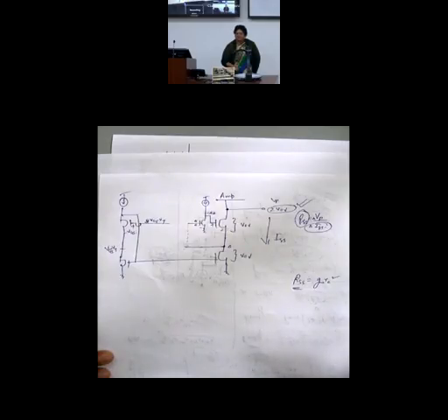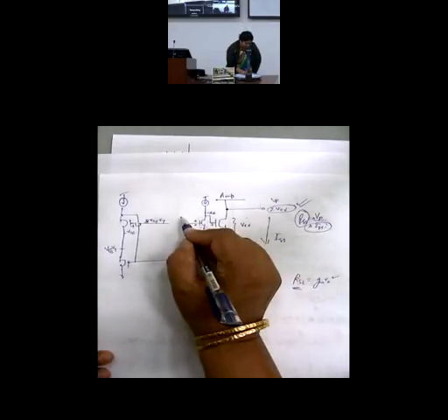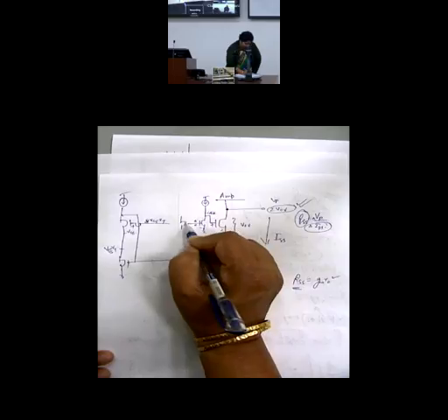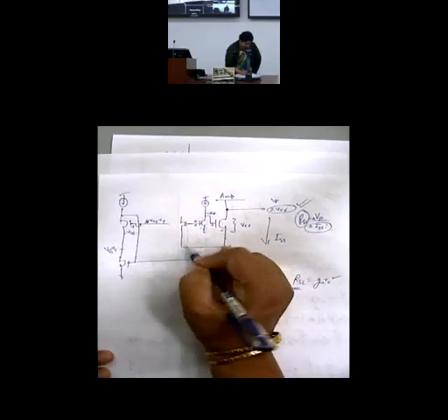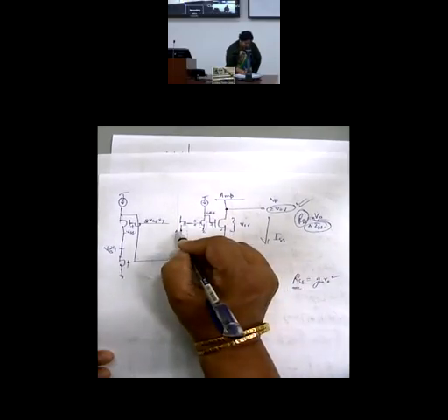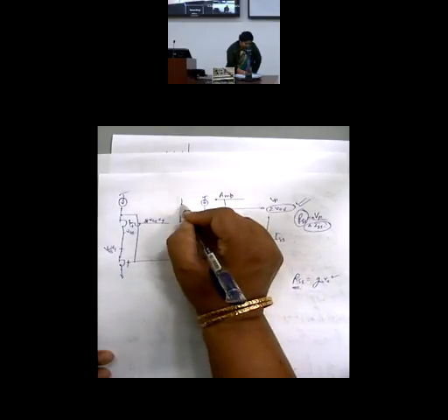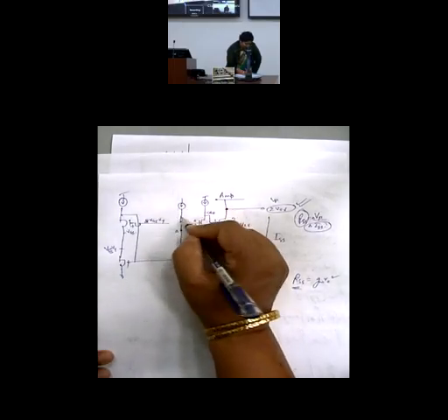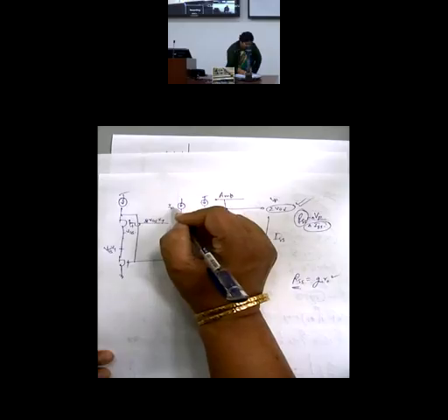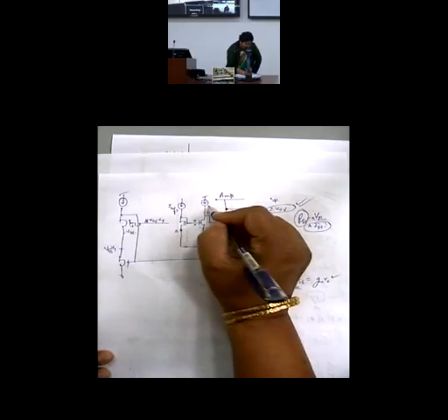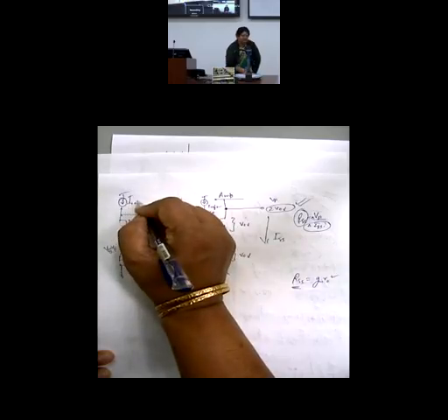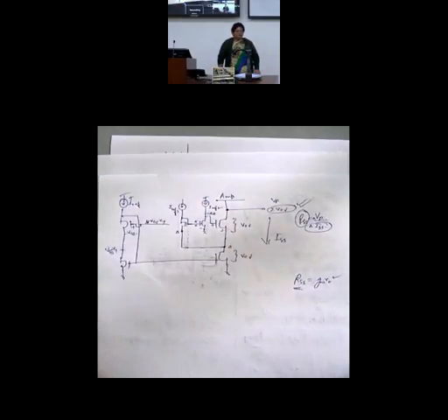Again, I get a concept from Wilson where we have a propagation of the voltage. I make a diode connected MOSFET here and I connect this. So this is now delta, and this I make to have a constant current flow, maybe IREF3. These IREFs can be different. I can create multiple current mirror arms and change my W by L ratios to tap multiple IREFs.